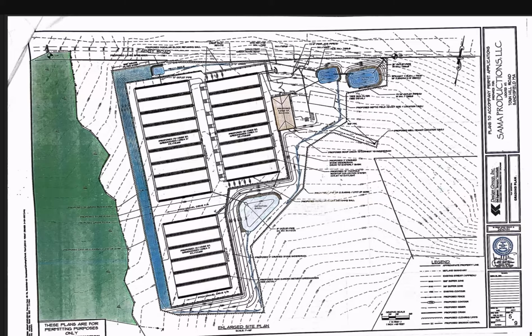So as the north and south pods, which are on the left towards the wetland, there's quite a space between them. And the reason for that is the grade change. So as I create more pods, every pod has a setback to allow that elevation change to occur and for a vehicle to drive around the site with some degree of comfort. You can't have vehicles trying to drive over a 2-foot high speed bump kind of a thing.